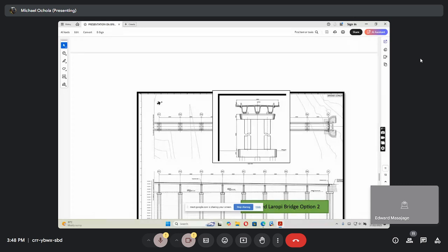Then you prepare formwork. These girders will take care of wet concrete, construction loading, everything from up. So they are precast and post-tensioned. That's how they look alike, but they're different in construction and even in design. So this is another, and we may go in for this one. We have weighed the two and realized that maybe this might seem to be cheaper.